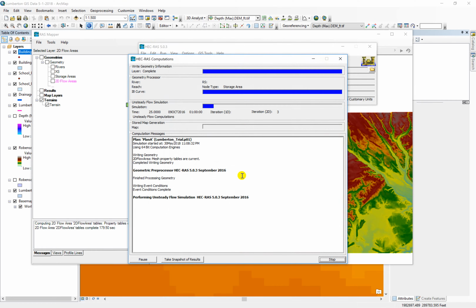Do you know how long it might take? It depends on the time interval that you choose. We chose 1 hour, so it will not take time. Yeah. Okay. Can you see here? If we define it as 15 minutes, I would have to leave my PC, run it, and come back the next day. Yeah. And it depends on the mesh size also, because we defined it as 300 feet. In my model it is 100 feet.